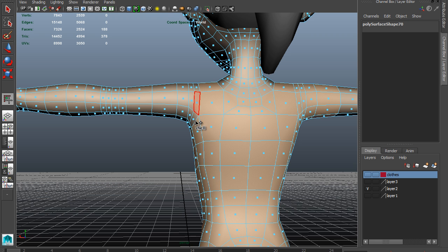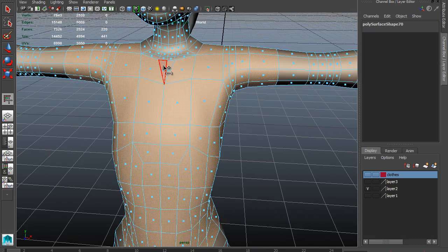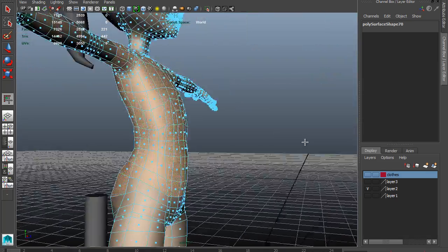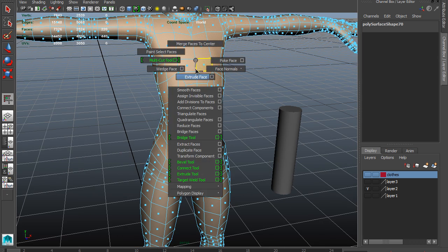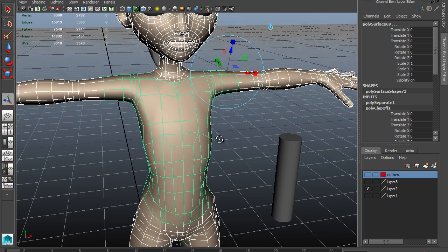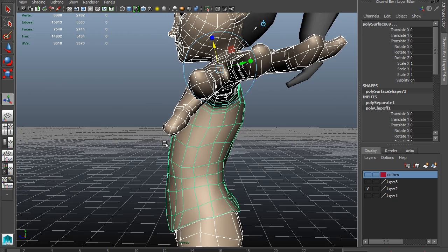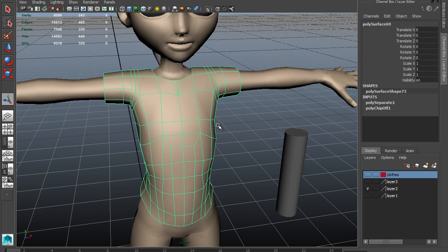Okay, same thing on this side. Okay, so that set of selections, and make sure that's the only stuff I have selected, which it is. There we go. I'm going to extract that, or duplicate the faces. That's probably the best option. I'm going to say duplicate faces, and I'm going to pull along the z-axis up. That's going to give me an inflated version of the same mesh, but now there are two separate models.